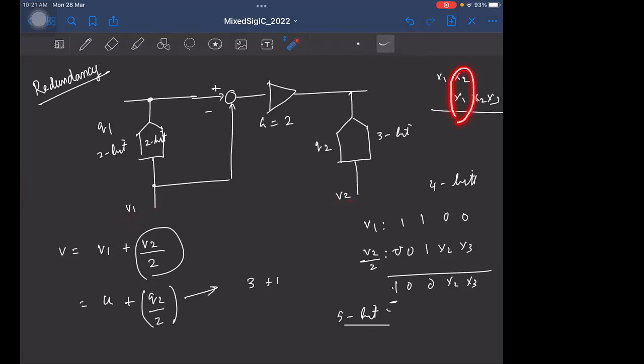So earlier you saw that you can just simply concatenate the ADC outputs. But here, since you have a gain that is less than 2 power B1, when you combine the digital outputs, there will be 1 bit of overlap here. So essentially, you need an adder. Okay. And the output of this addition operation can in turn have 5 bits. But it can have only 16 possible output codes.